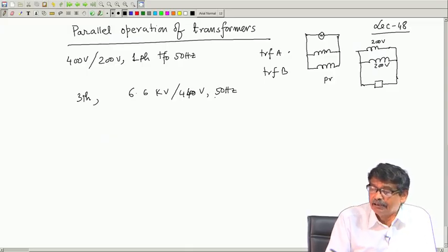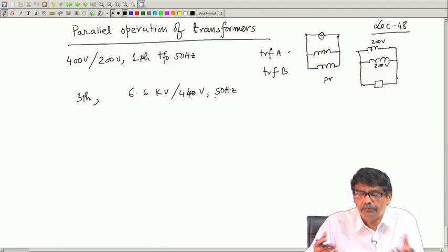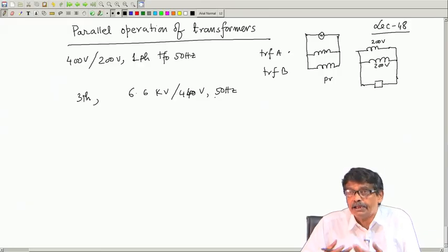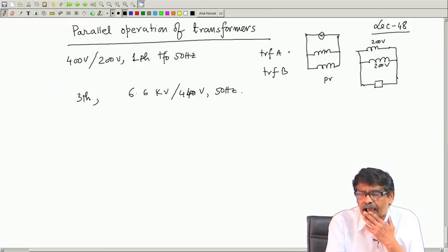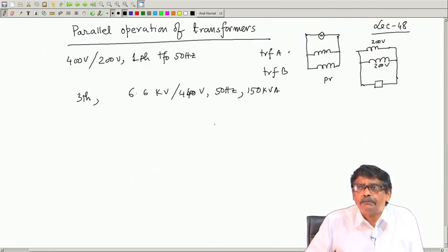Now, suppose you see that presently the kVA rating of say 100 kVA will be sufficient to cater to the consumers, but it is a growing area and the load demand is growing. So, suppose you decide, okay, I will now buy a 150 kVA transformer, with 50 kVA as a margin, and start giving power to the consumers.